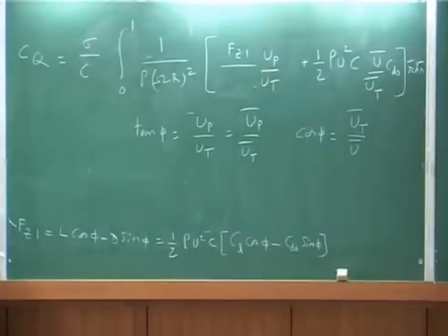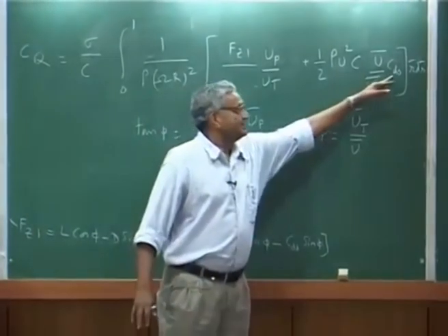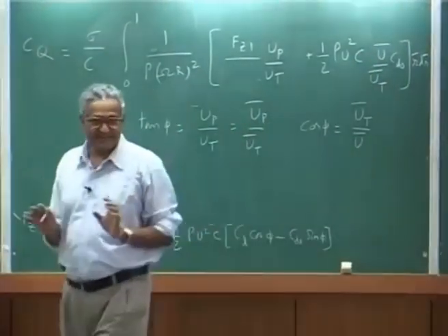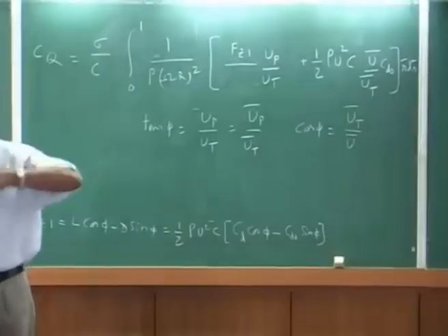You can put a bar, finally you will find that it will get nicely cancelled and come into a nice clean form. Now, this is the torque. It has two components, one due to the profile drag C d naught, another due to the thrust part.